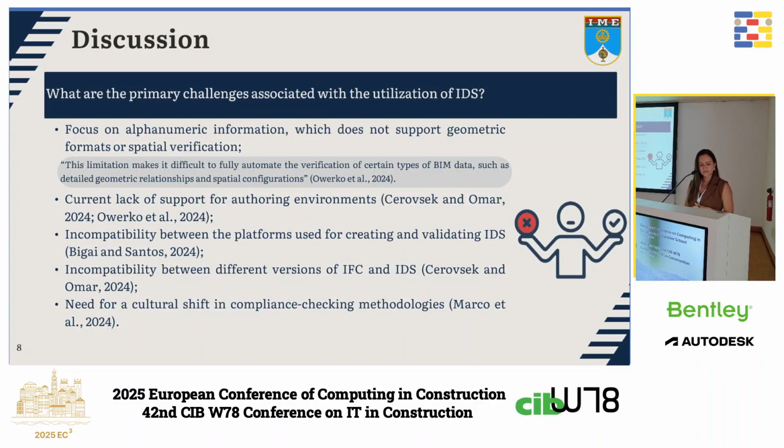The second question was about the primary challenges associated with the use of IDS. One of the main limitations is that IDS focuses only on alphanumeric information and doesn't support geometric formats or spatial verification, which may restrict its applicability in certain model checks.